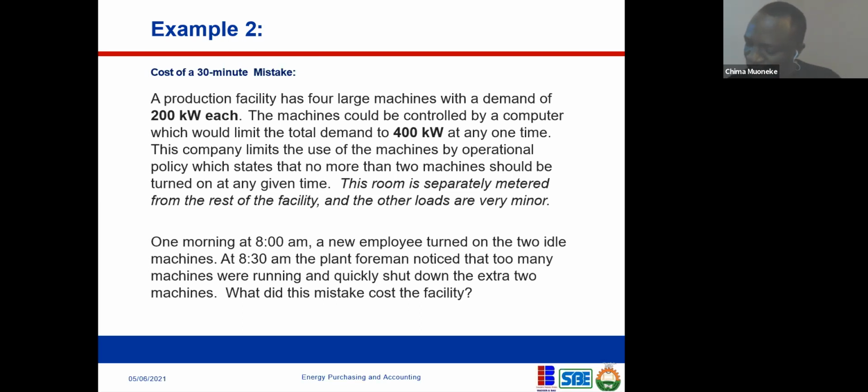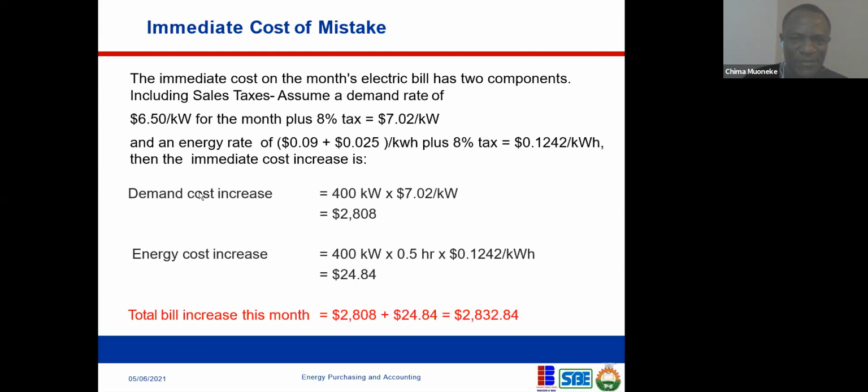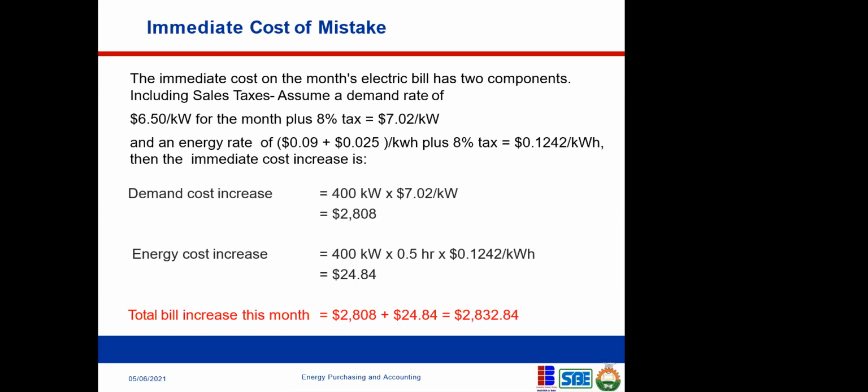Now multiply that 200 kilowatt hours by the energy charge. Let me see what the energy charge is from the solution. The energy charge is the same as in the old solution, which is 0.09. Let me add the fuel adjustment, or do you want us to do it separately? Let's do it separately so that we follow it step by step.